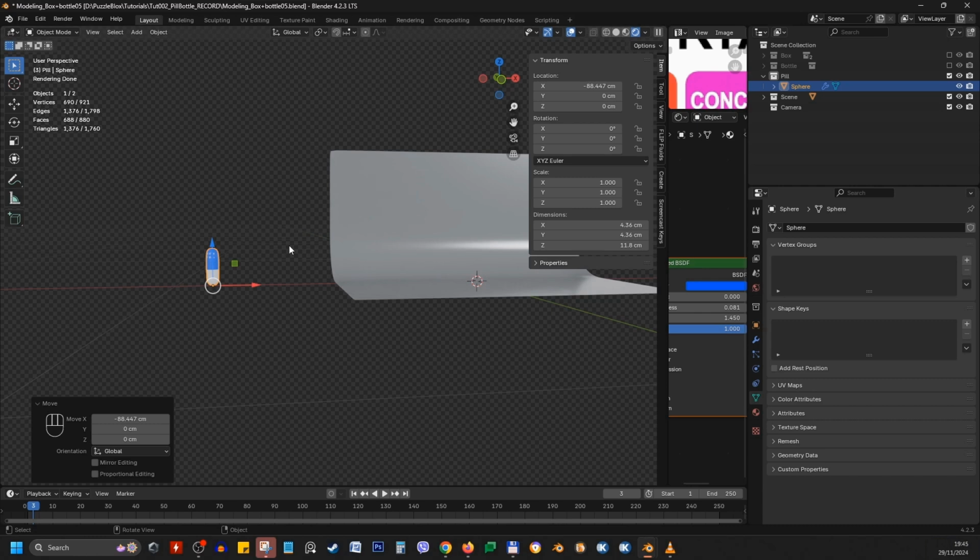So for this particle system to work the same as this tutorial, you need to get the scale and size of this pill same as you see in this tutorial. Try to get it as close as possible. So first of all, scale it in object mode, not in edit mode, and get the scale to 1.832.